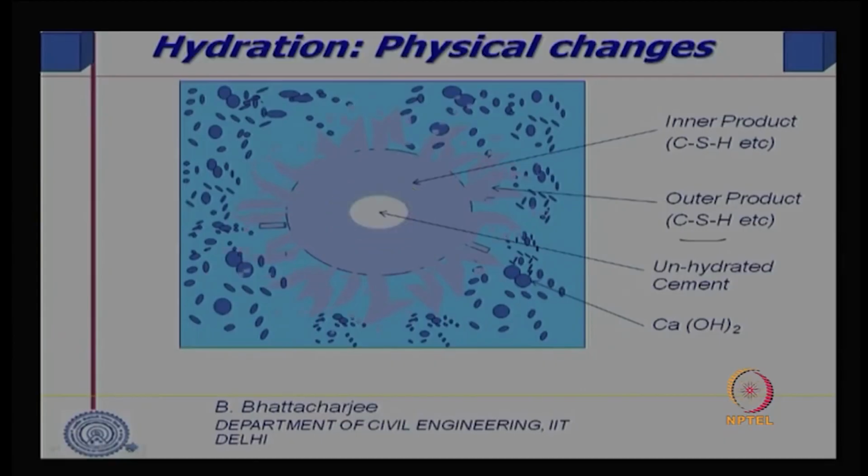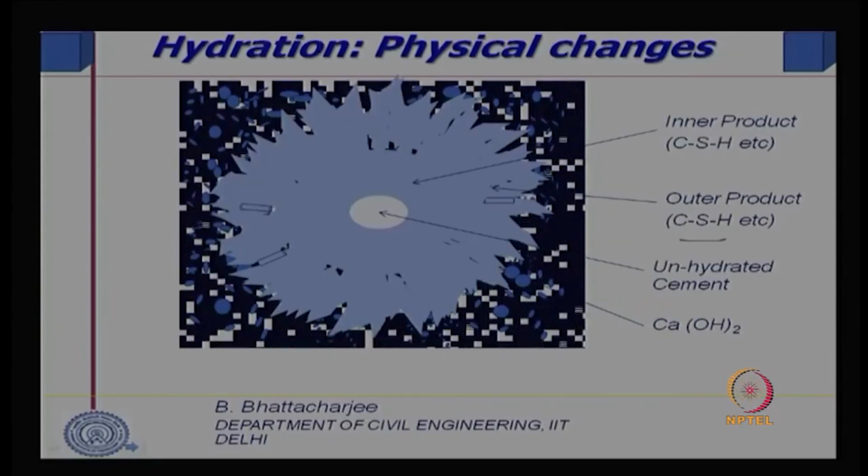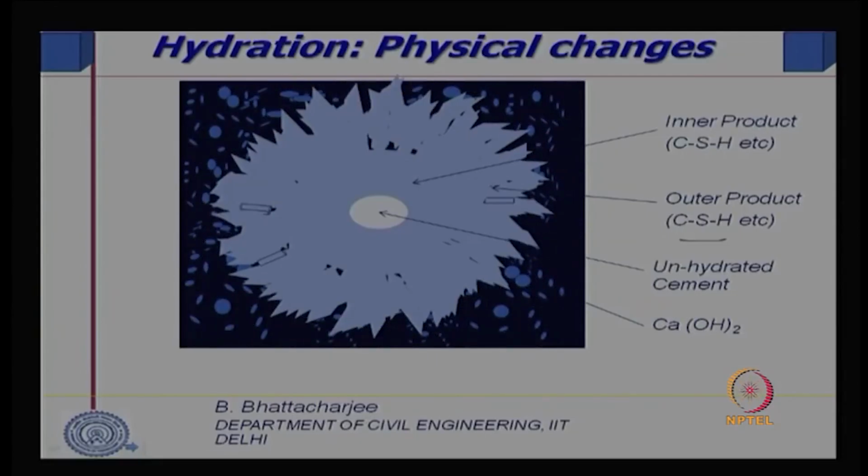Let us say further reaction starts occurring. So, unhydrated cement now gets reduced and CSH outer product now increases to a large scale, and you will still have this calcium hydroxide precipitate outside. The black portion, if the hydration has now stopped, represents blank space which will remain as pores. They have become black from the blue water; finally, the water has evaporated and that has become pores.